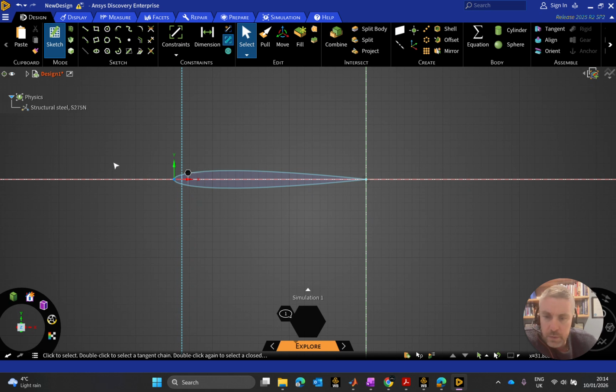But what does happen here is that as the air is kicked up a wee bit, a pressure gradient builds up across these streamlines, which are immediately affected. Now the air up here doesn't change pressure much; it's still free stream pressure, as is down here. But within this area, not within the boundary layer, just above it, there will be a pressure gradient across these immediate streamlines, and it is that pressure gradient that pulls that down.